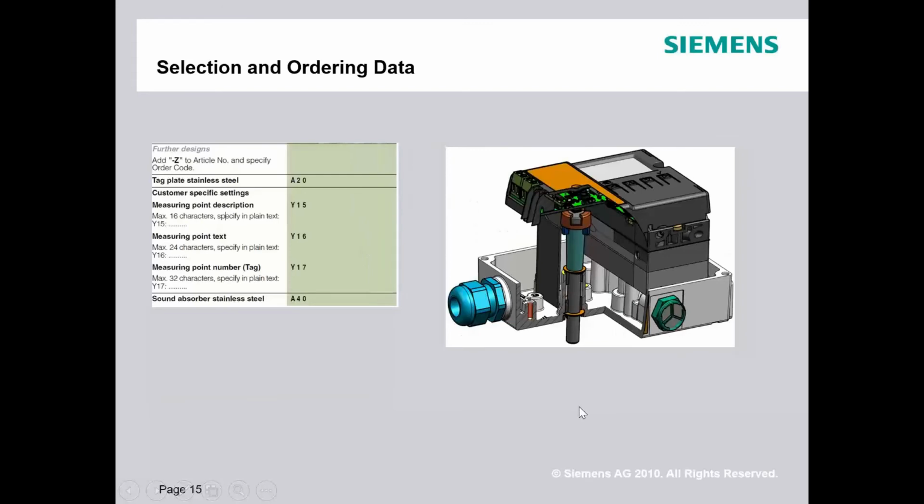All right. If you look at this cutaway, what you see here is the magic piezo block. One thing this positioner has, which I really, really like, is this. That's the shaft that would go to the mounting lever or whatever. This is your feedback. This is what tells the positioner exactly where the valve really is. Like Matt was saying, if you didn't have that, you could have an output, but you really would never know if the valve was where it was supposed to be because there's no feedback. All right. The heart of this is this part right here.